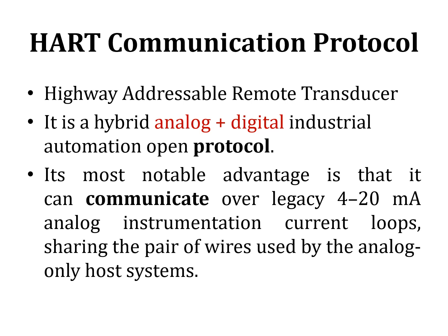It is a hybrid system in which analog and digital industrial automation is used, and it is an open protocol. The best advantage of this protocol is that it can communicate over and above the 4 to 20 milliampere analog instrumentation current loop. So we have the advantage of the 4 to 20 milliampere loop as well as overlapping digital communication over it.